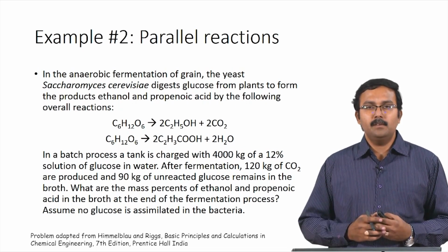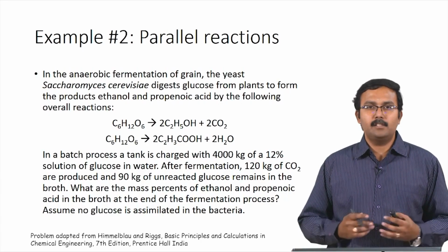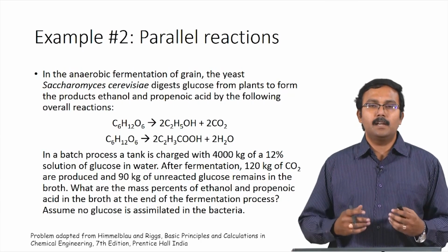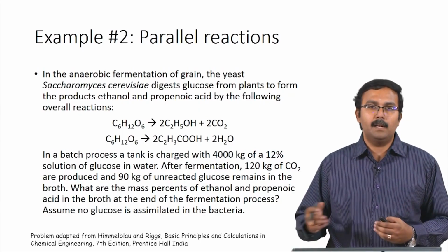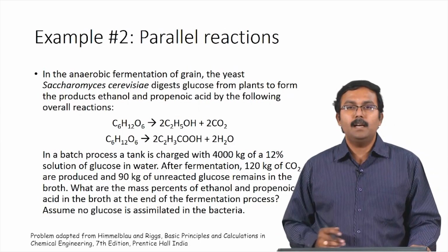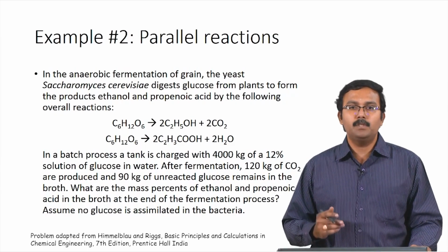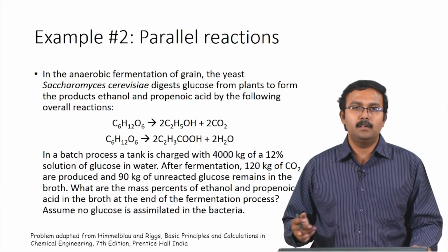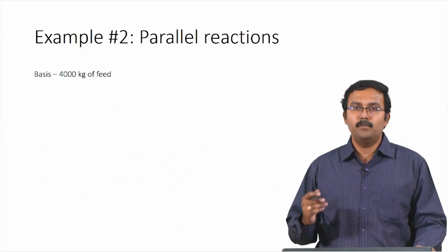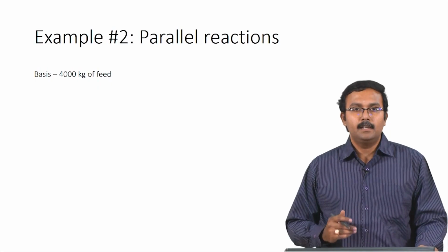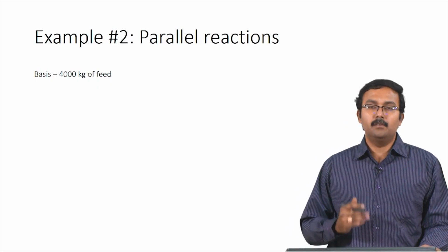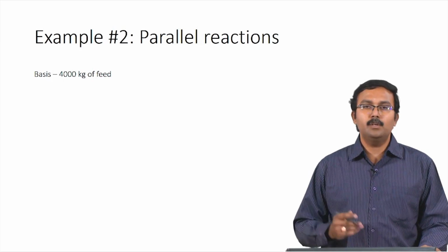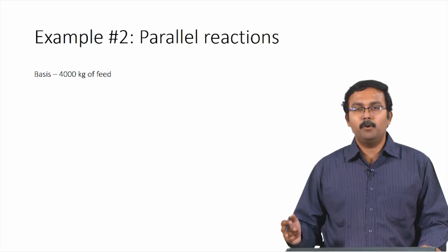So as I mentioned, we will try to use a technique called extent of reaction technique. We have already defined what extent of reaction is. We will try to apply that for performing these material balance calculations. To start the problem, we identify that 4000 kilograms of solution is present initially in the reactor. So the basis would be 4000 kilograms of feed. Now that we have the feed in mass, we will have to identify how much of it is glucose and what is the amount of water.